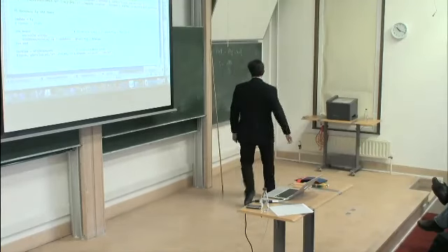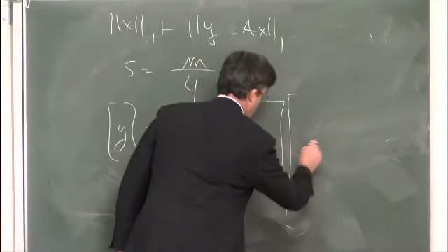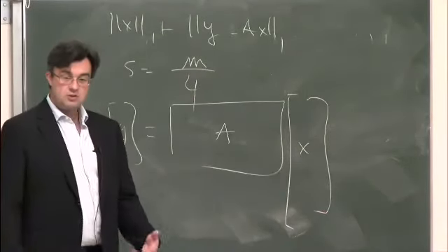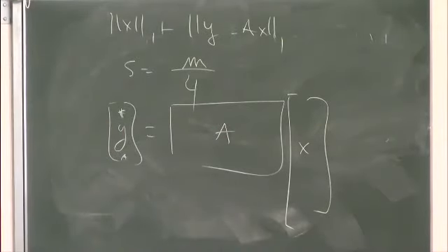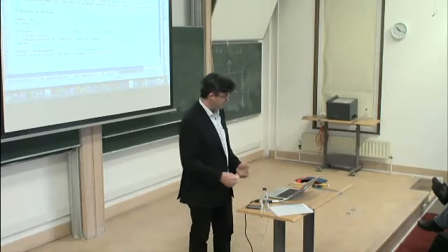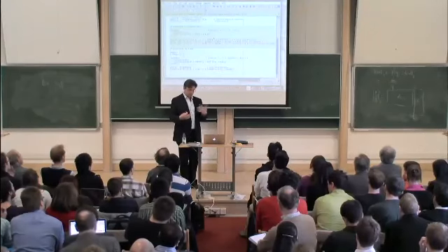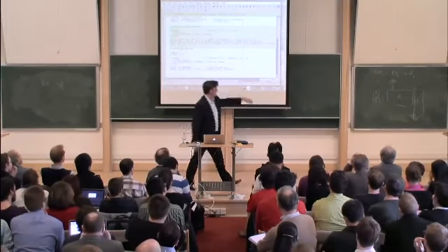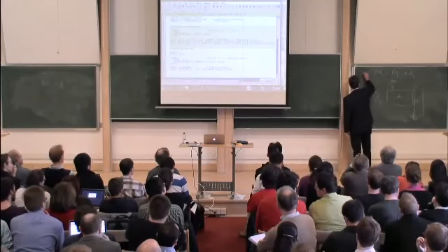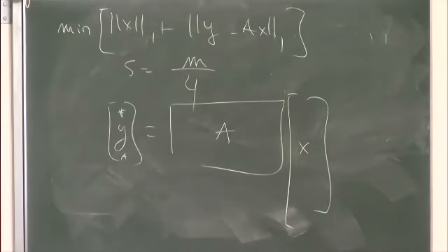So you understand, right? You used your compressed sensing mechanism to send your signal. And then the problem is that some sensor failed, you don't know which ones. And so some values in y have nothing to do with what they should be, but you have no idea which ones. Okay, so that's called impulse noise. But you don't know which entries have been corrupted. Most of the sensors are performing okay, some of them are not, and you have no idea, and you would still like to recover. You have an underdetermined equation, 10% of the equations are corrupted, let's say, and you still would like to do well. And so now to do well, we're going to minimize simply the one norm of x plus the one norm of y minus Ax. Okay, that's what we're going to do. So let's do that. Okay, so something is going to run, yeah.